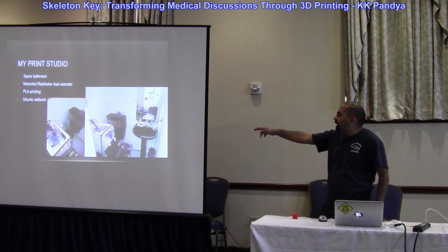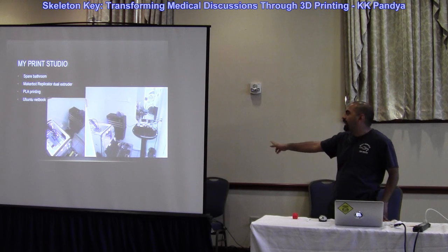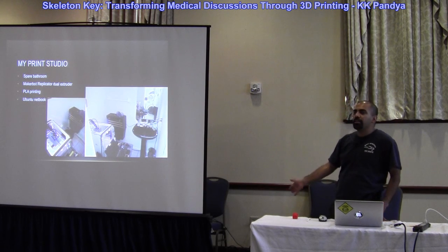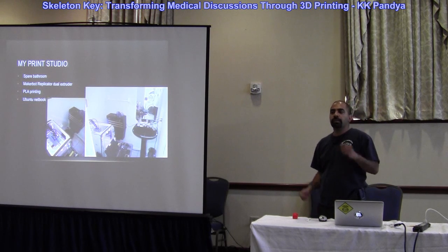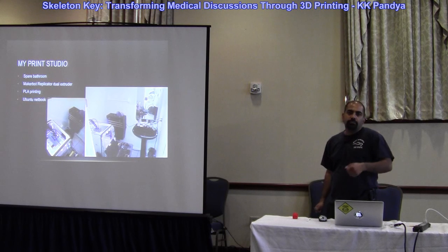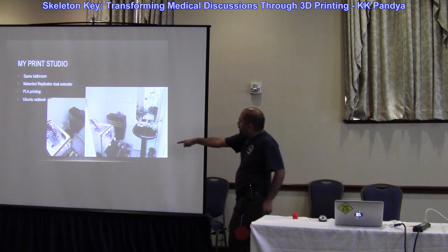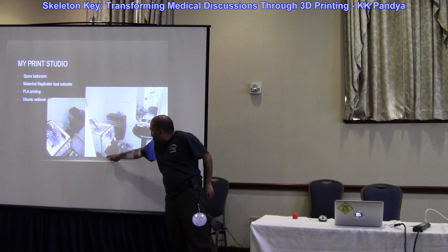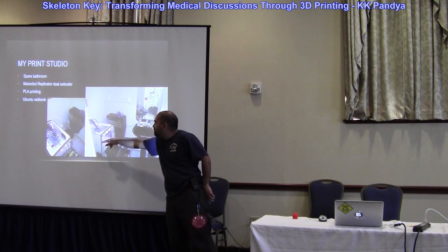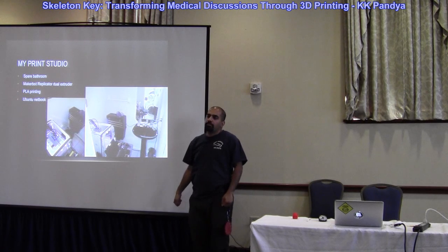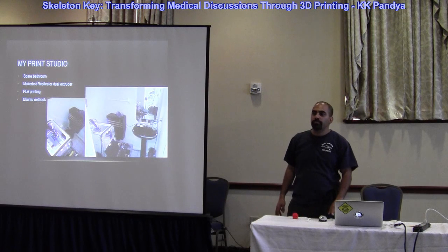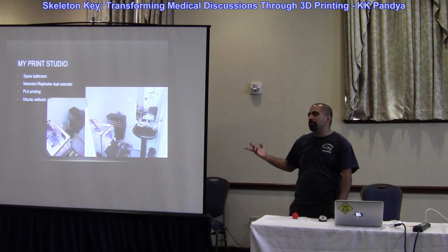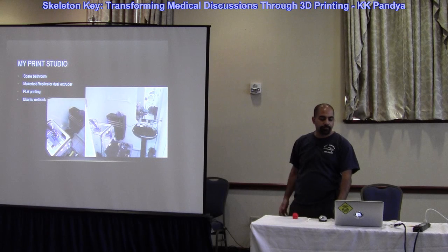So the printer from the ground up, I have foam pads, then a Rubbermaid cart with about 200 pounds of bricks on it, and then the printer itself is on another layer of foam and some wide feet. And then I have the whole unit bungeed down to the cart. So it isolates from vibration from outside in the room and dampens a fair amount of the machine's motion itself.